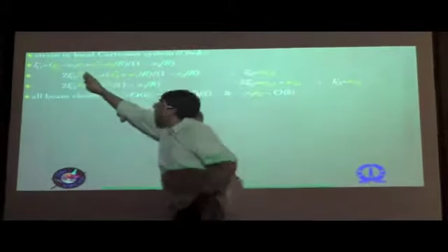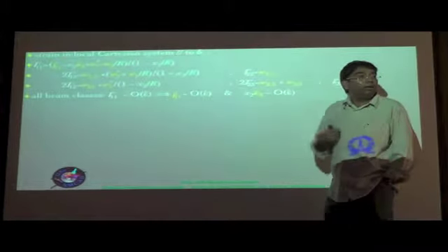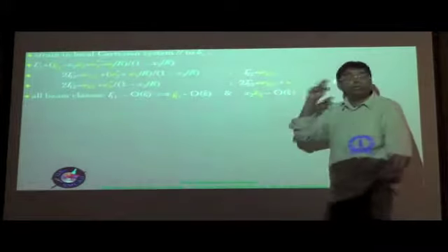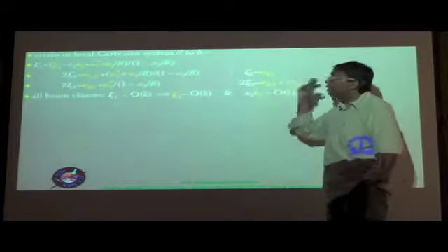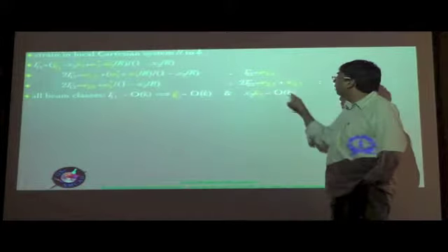Next, coming to this term that you have here, x2 times kappa 3 bar as a product should be of the order of epsilon hat. So from that we can detect the order of kappa 3 bar. We are considering class R beams. So both x2 and x3 are of the order of A. So in other words, your kappa 3 bar would be epsilon hat divided by A.